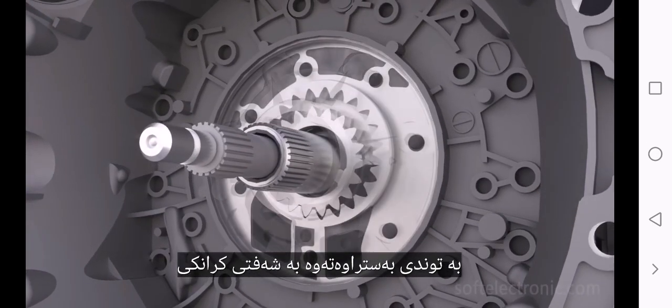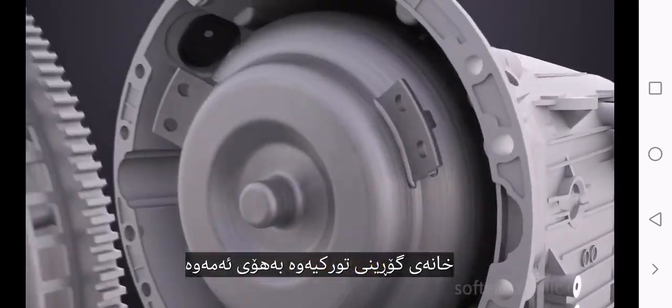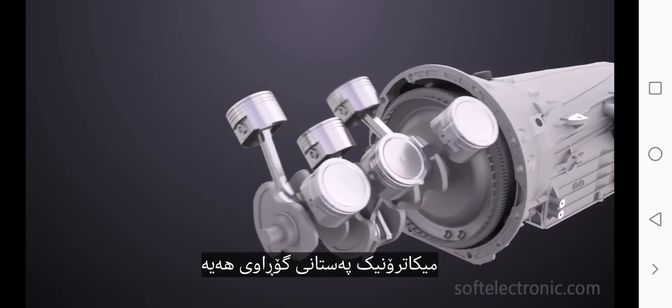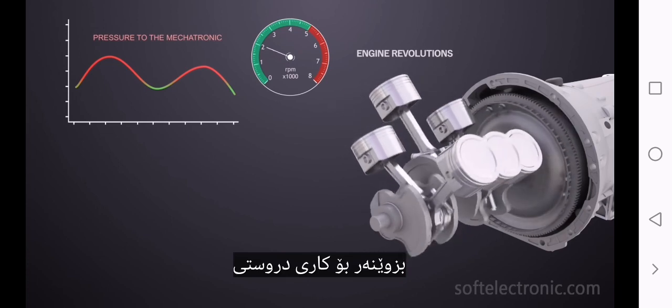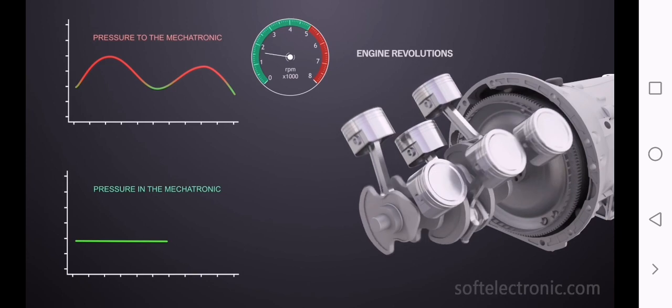The fluid pump is firmly attached to the crankshaft of the engine via the torque converter housing. Because of this, the fluid which is fed from the pump to the mechatronic has variable pressure depending on the revolutions of the engine. For the proper work of the automatic transmission, it's necessary to have constant and invariable working pressure.